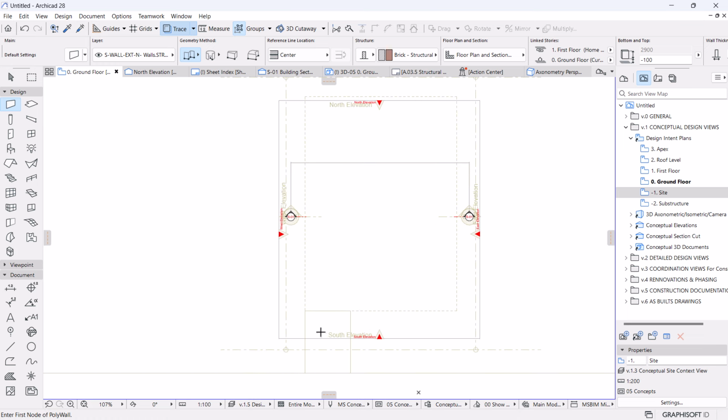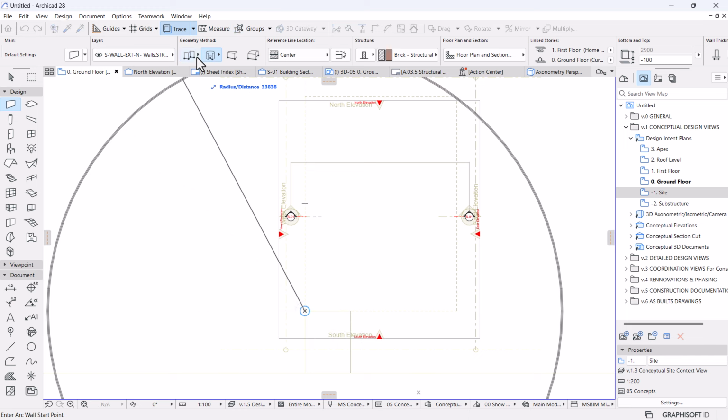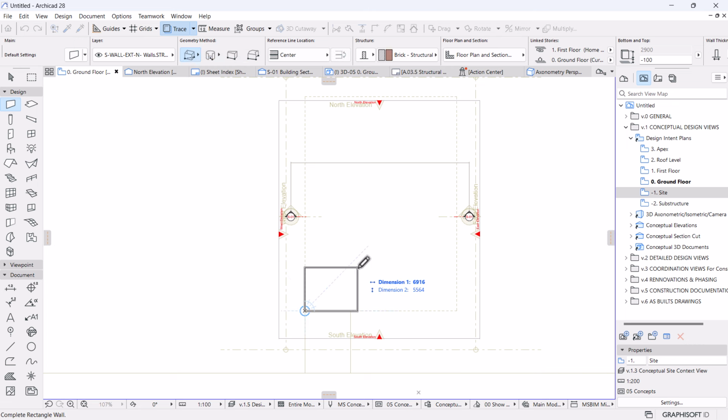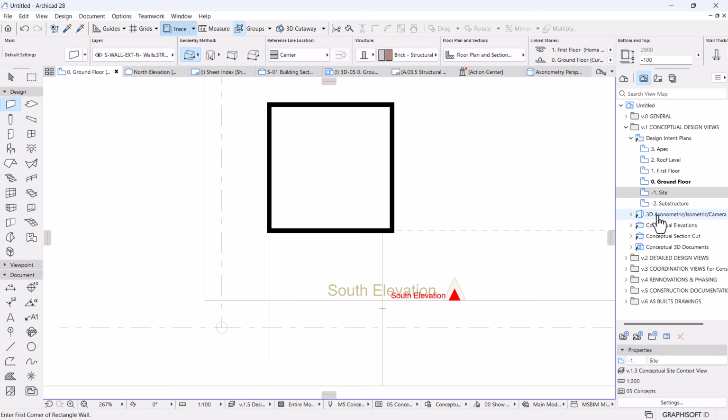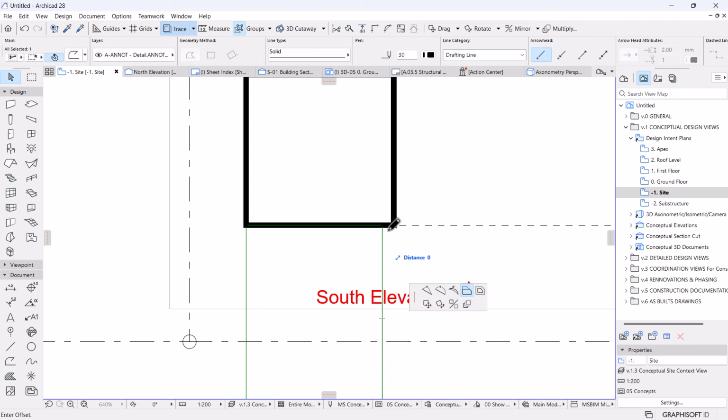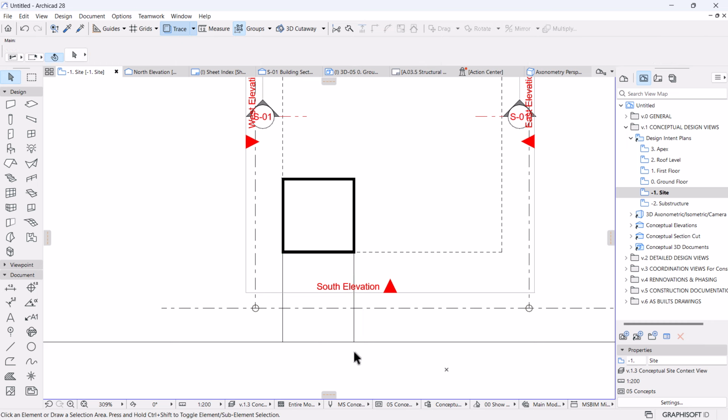I'm going to start with the garage position. Like I mentioned before, the access of the plot influences the position of the garage, so definitely it will be here. So I'm going to draw a box. Let's change this to a rectangle, and then I'm going to draw a box for this garage, 6.5 width by 6.5. This is a decent space to fit especially trucks and vans within your garage. So I think I'll go at this much and then hit enter. So that will be the position of the garage, right? You could see even now the driveway could adjust a little bit. So I'm going to go to the site, then adjust the driveway to the new position of the garage.